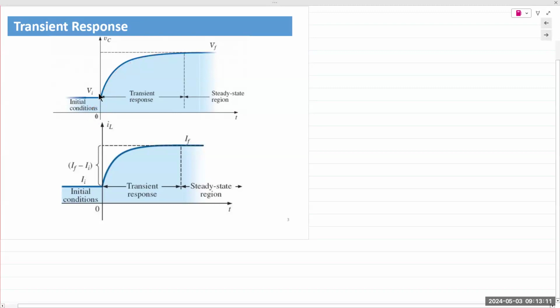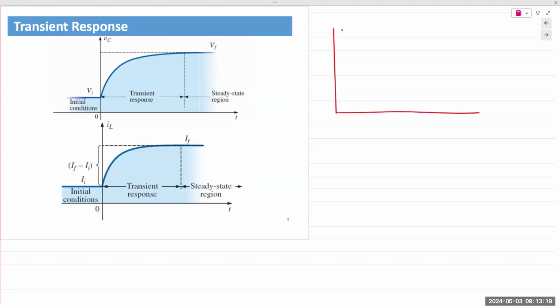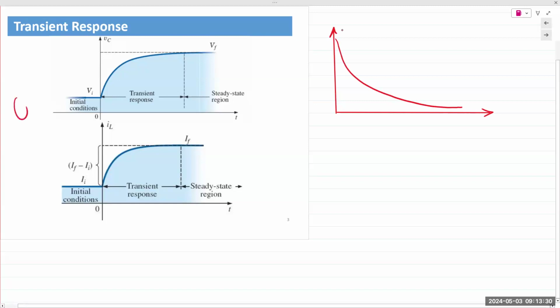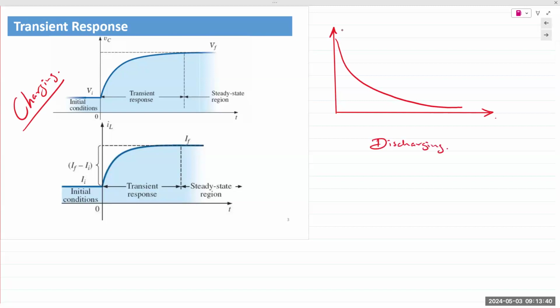The discharging phase follows a similar pathway, and you again have an exponential relationship with respect to time. Both of these are showing the charging waveforms. This is the discharge. Time is here. This could be describing voltage or current, but they always have an exponential relationship with time.